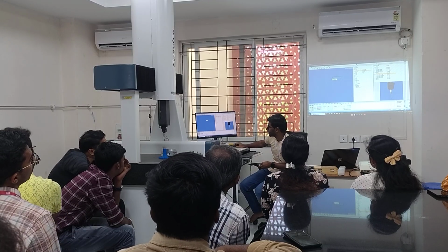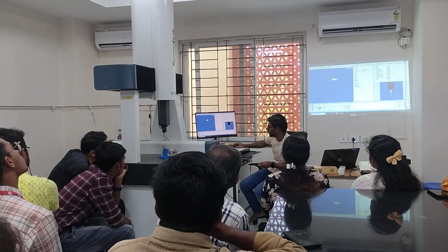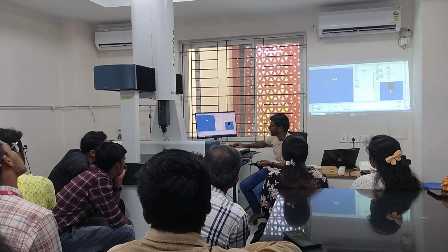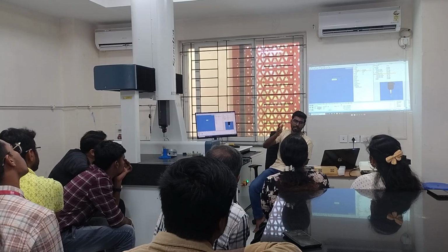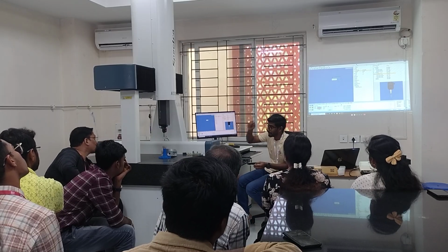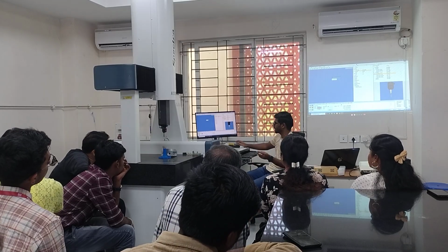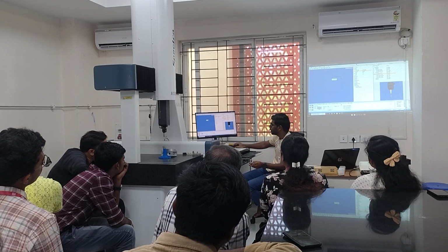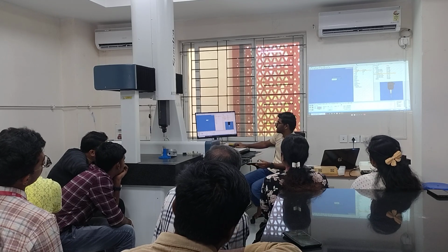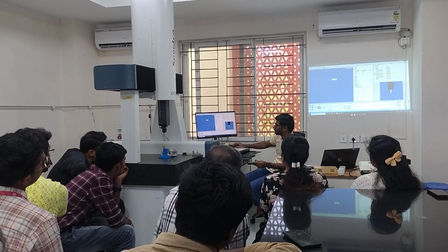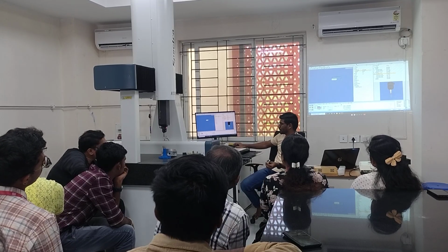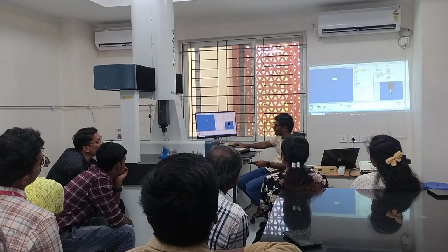But how much are we getting? It is 50.417437 degrees. Okay, so there is some deviation. That shows that additive actually is not perfect, even though that is an SLA part. In the drawing, it might sometimes say that the tolerance limit is different, so you can change the acceptable or non-acceptable limits. Okay, I click on accept.